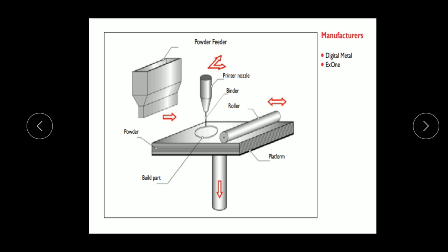Subsequently, the feeder feeds the new particle material onto the design cavity to develop the first layer as per the design consideration. Now the platform is moved down and the process repeats until the formation of the 3D object. I hope you understand how the DMLS process works to produce 3D components.